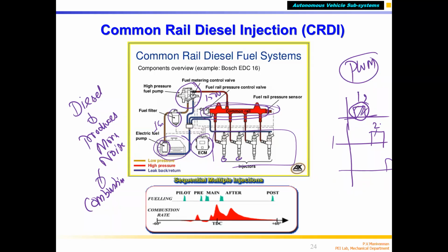So when the fuel is injected at 1,500 bar using the injector, the fuel droplet may be 20 micron to 10 micron, which is much smaller than the unit injector. So when combustion happens with a smaller droplet size, the combustion noise reduces. That's why in the latest generation CRDi engines, you will see the noise is very smooth. You won't get much noise.